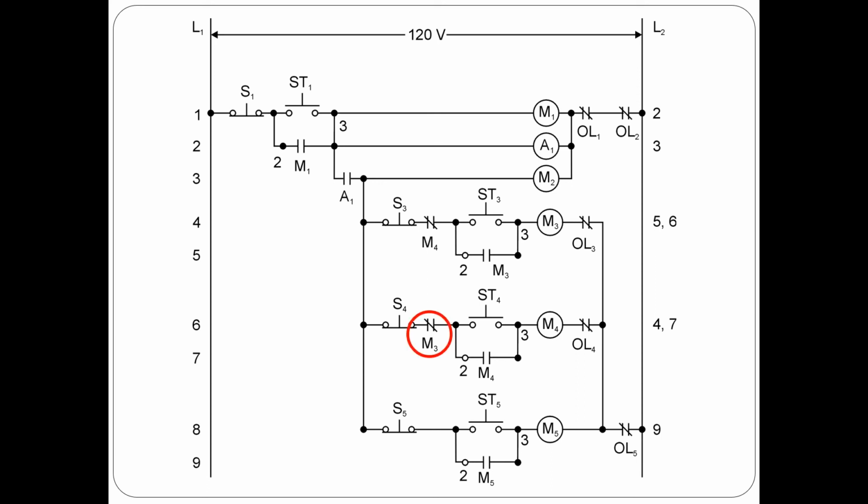If you remember when we first looked at this circuit, we identified the normally closed contacts M3 and M4 as being interlock contacts. Since they're both normally closed contacts, this tells me that both M3 and M4 should not run at the same time. They should be locking each other out. So therefore, if I can operate M3, and then I can still start M4, that tells me my interlocking for M4 doesn't work, which also tells me that the normally closed contact M3 is going to be faulty.